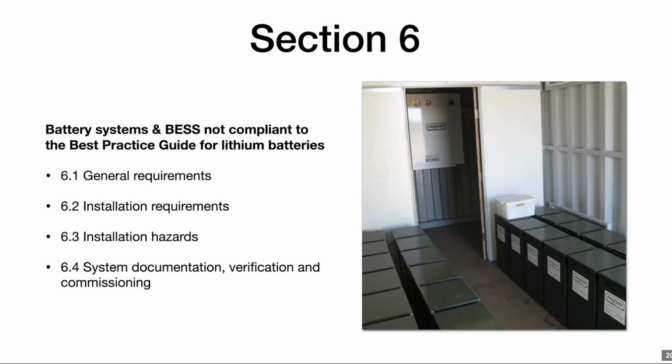Section 4 was for pre-assembled battery energy storage systems. That would be a package manufactured to a standard, tested to a standard and compliant with the best practice guide. That's a very limited set. Really, it's products that are like an all-in-one solution, like an Alpha ESS, eStore, like a Sonnen, like a Varta package, like a Tesla Powerwall. They're all pre-assembled BESSes because they've got the PCE as part of the product. There's no on-site manufacture of components. You are just mounting it and connecting it.